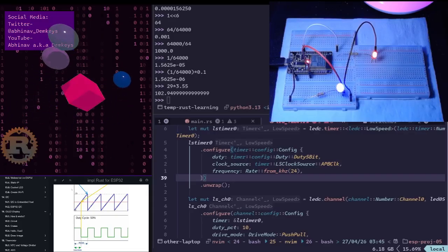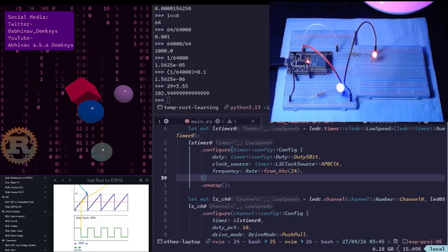So, direct memory access. This is the ultimate independent worker. Usually, if you want to move data from a sensor to the memory, the CPU has to pick up every single byte and move it. With direct memory access, the CPU says, "Hey, DMA, take the next 1,000 bytes from the radio and put them in this folder. Wake me up when you're finished." The CPU then goes to sleep and the DMA hardware moves the data byte by byte in the background.